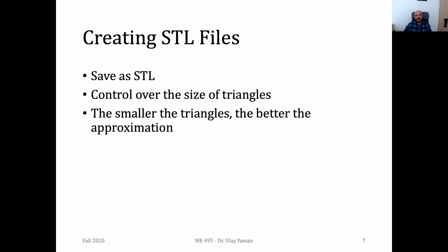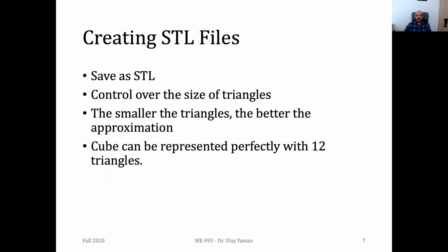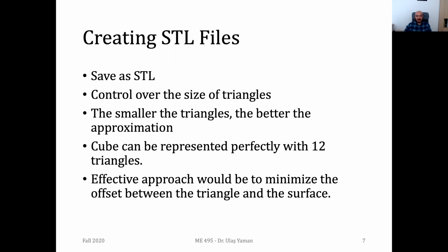And we know that if you have more triangles, the size of triangles becomes smaller, then the approximation will be better. But if the number of triangles is less, then the quality will be lower. And as you know, in the cubes we have 6 faces, and you can simply represent each face with 2 triangles, and that makes 12 triangles for a given box shape.